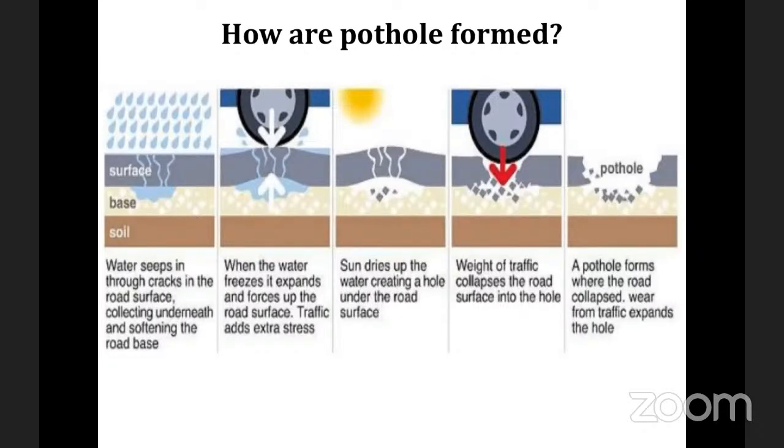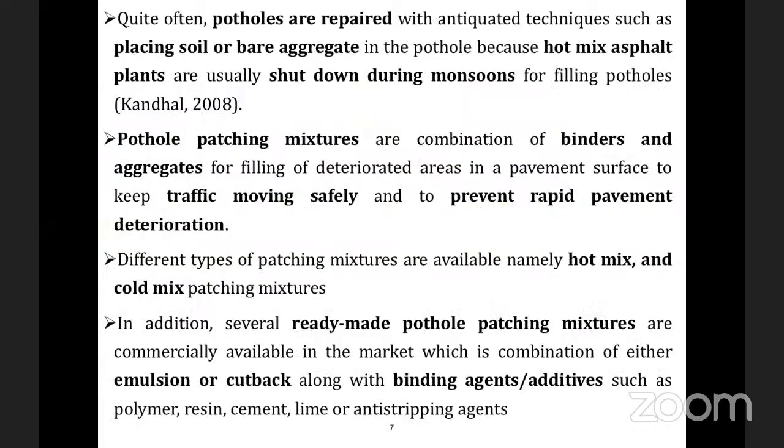Along with the water, as there is accelerated traffic load, this causes the formation of a pothole, as we see here. So the main culprits are the water and the traffic load, and the other is adverse weather conditions, one being freezing and one being dry. This picture shows how these potholes are usually formed, and it is a bowl-shaped structure.